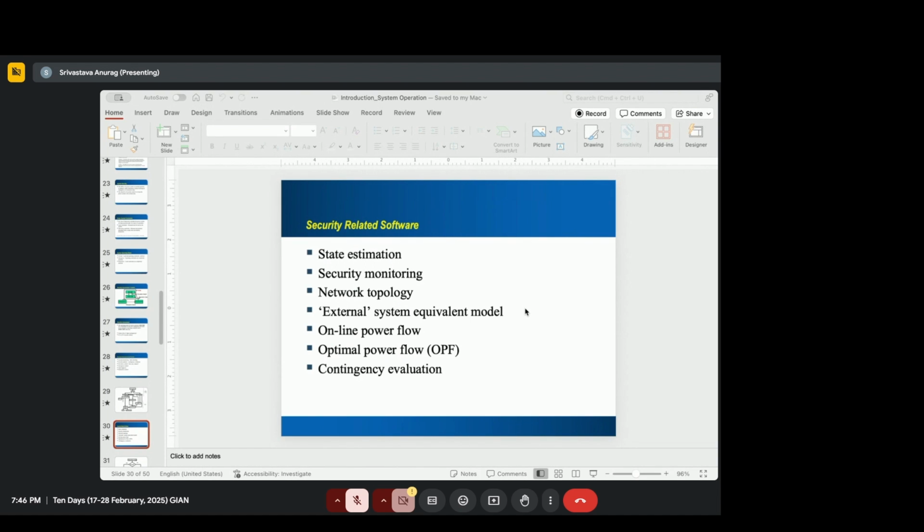There are some papers on that also. When we say real time, real time is defined in terms of being able to solve state estimation within a time you set. You tell the time that you want state estimation to solve in: 30 seconds, 5 seconds, 1 minute, right? Typically 30 seconds is okay, even though we can solve in 5 seconds, but we don't need to solve more quickly. So you have to set the time at 5 seconds, 10 seconds, 15 seconds, or 30 seconds. And then if you can bring the data and solve state estimation within that time, we'll call it real time.